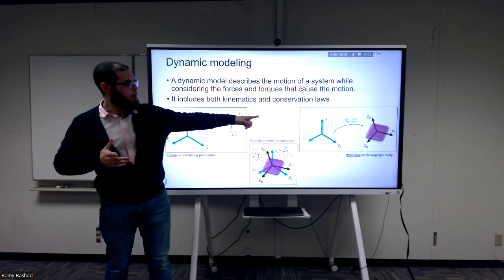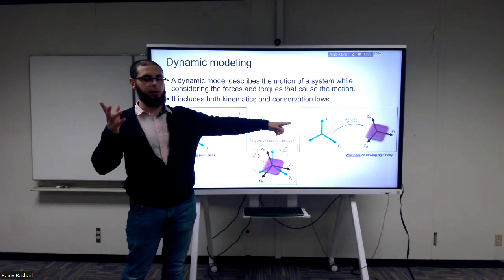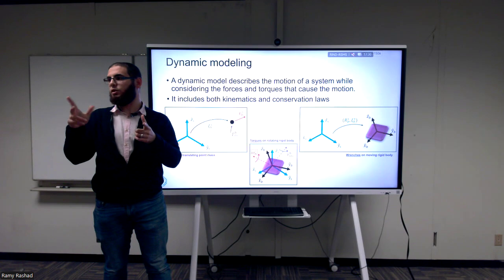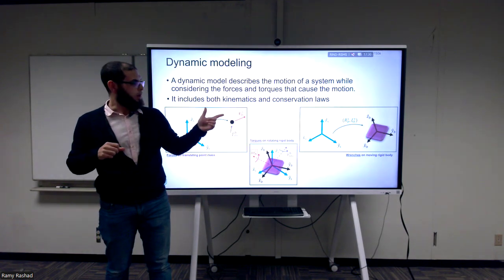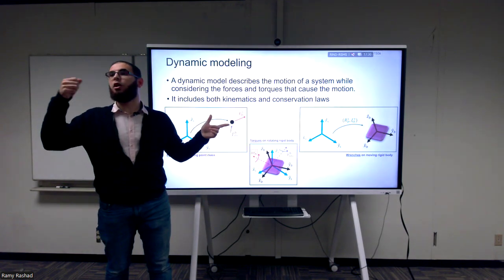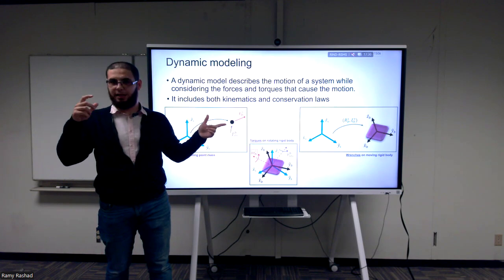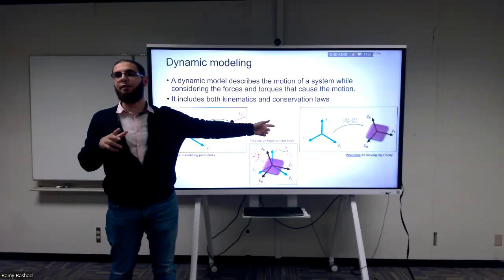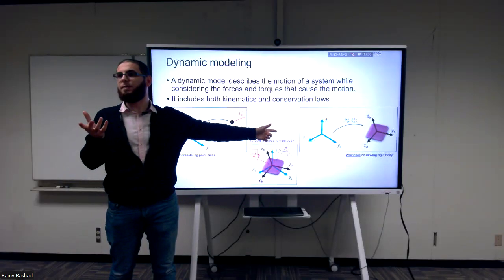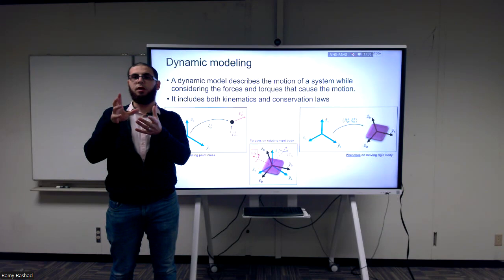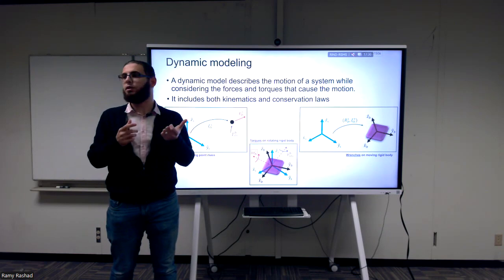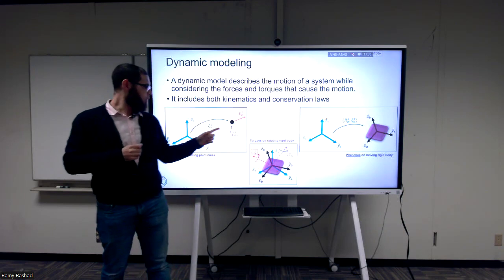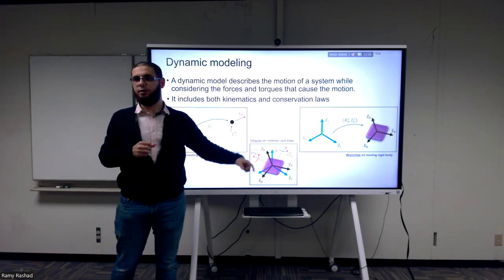When we used homogeneous transformations to describe rigid body motion, translation and rotation, we had the generalized velocities, the twist, which described angular velocity and linear velocity. Then you can expect that here we're going to have some quantity that corresponds to a combination of forces and torques. We're going to call this quantity wrenches. Okay, so forces, torques, and wrenches.